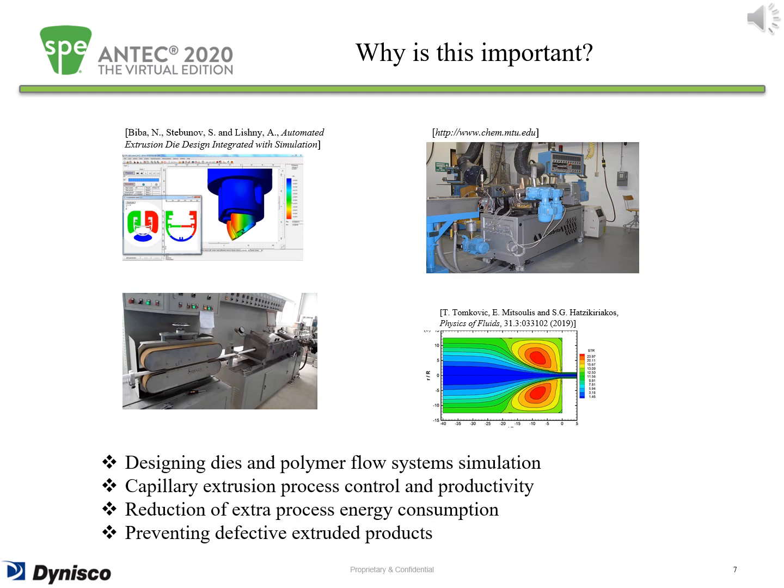But why is this subject important? Analyzing the elastic properties and predicting the entrance flow pattern of viscoelastic polymer melts is important for designing dies and flow systems in process simulation purposes. Another benefit is for extrusion process control. This is even more essential for the processes that are involved with a stretching of polymer melt, such as tube extrusion or extrusion blow molding.